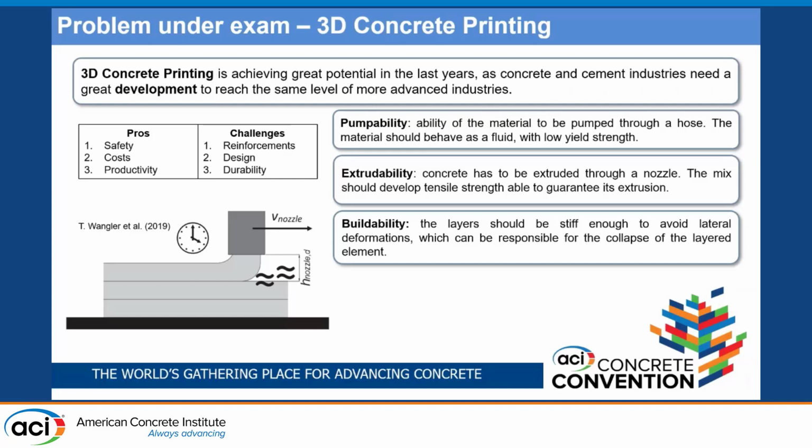On the other side, there are some other challenges that we still have to face. For example, how to place reinforcements during the construction, during the printing of concrete. Are the design methods that we have today for designing reinforced concrete elements still reliable for 3D concrete printing? It's a very good question. And durability, because of the interfaces. For example, here in this picture, you can see that in between layers there are interfaces that can reduce the durability of concrete printed elements.